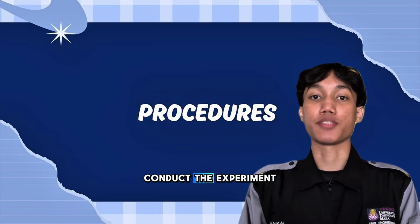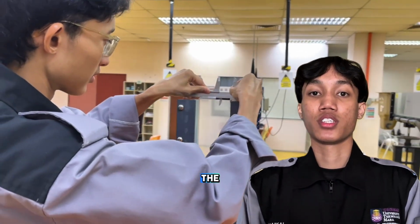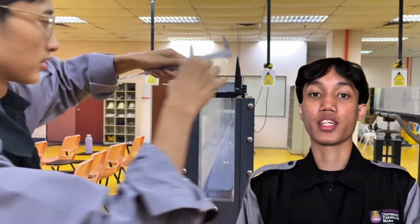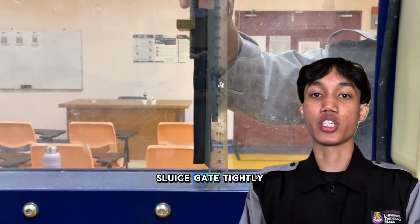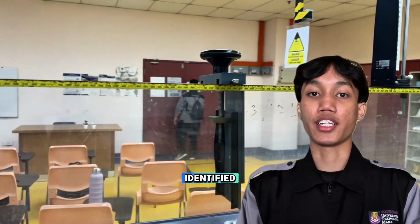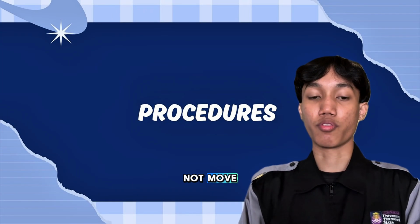The first step to conduct the experiment is we must measure the width of the rectangular open channel by using the vernier caliper. The width of the rectangular open channel is 7.76 cm. Next, we set the height of the sluice gate to 10, 20 and 30 mm and the sluice gate is positioned at the identified location in the rectangular open channel and screwed tightly to ensure the sluice gate does not move.